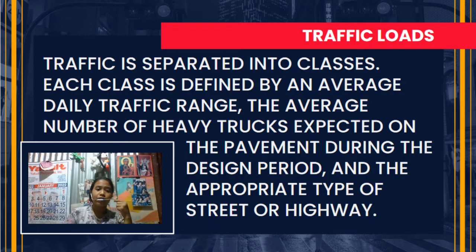Class 5 is heavy, up to 9,500 autos per day, 2 million to 5 million trucks expected during design period. Urban freeways, expressways, and other principal arterial highways. Local industrial streets, major service drives or entrances, airports, 60,000 pounds maximum gross weight.